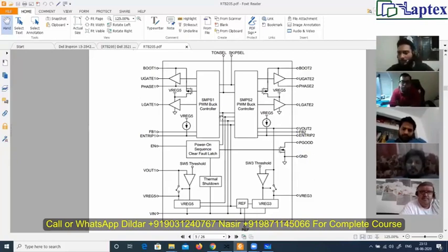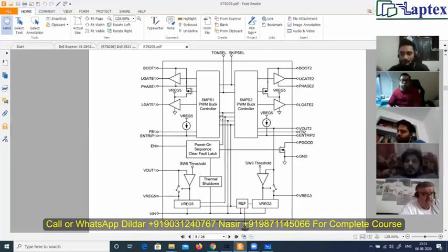If he wants to enable the IC by the enable pin, he will provide the supply from the enable pin. If he wants to enable it from the VIN supply only, he will remove the enable pin and supply directly from the VIN supply. So an LDO can be enabled with the VIN supply as well. Remember this point: the 3 volt, 5 volt coil voltage will never be enabled by the 19 volt VIN supply. It will require a different logic other than the LDO supplies. Getting the point?